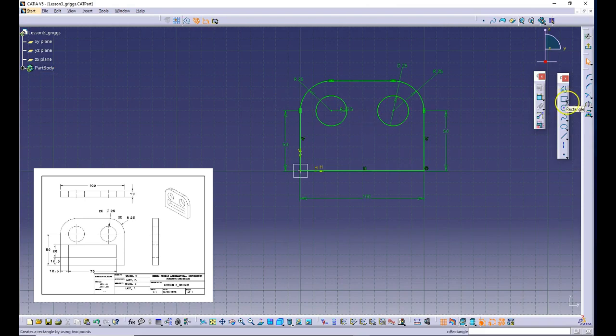So one more thing, the rectangle tool, we've got, again, several different options under here. You can also make slots, elongated slots, keyholes, polygons of various sizes. But for the rectangle, let's go ahead and start with this one. I want to place it inside of my object right here. Try not to create any other constraints accidentally. So notice all these blue lines that come up trying to form constraints. So I'm going to place it where I don't have any of those, and then place my second endpoint across on the other side.